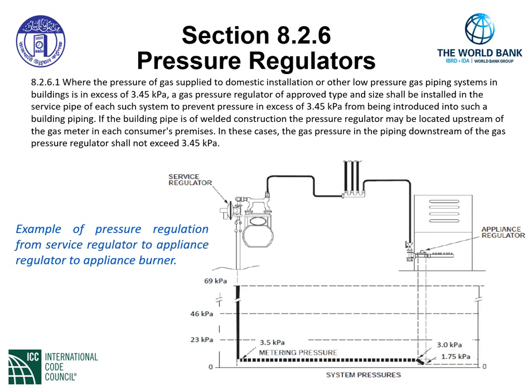As we go through the meter with the volume of gas under this pressure, 3.5 kPa, we emerge from the meter set into the gas piping system that goes through the manifold and up to the appliance regulator indicated in the appliance.